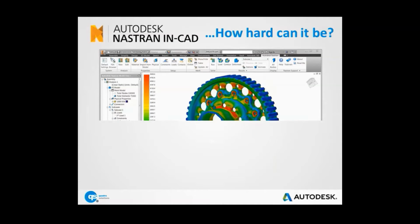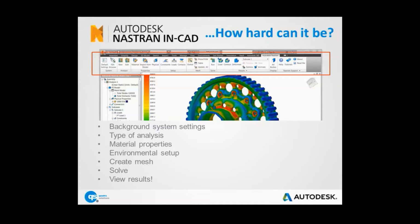Question, how hard can it be? In other words, is it hard to drive? No, absolutely not is the answer. As you'll see above, the standard ribbon is structured to be followed from left to right in such a way that it gives you a checklist of the process you need to follow to preload the right parameters. You start with the background system settings, then the type of analysis that you're doing. You then look at the material properties, the surrounding environment, then, providing that no guidance errors have been flagged up by the software at this stage, you proceed to mesh, then solve and view the results.